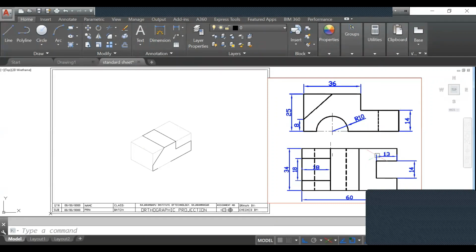So here, if you observe, for this hole, there is one hidden line. Means there is a C channel. The C part is there in the top view at a surface of 14 mm from the bottom, not at the top surface. It is on the 14 mm height only, not on 25 mm height. So I have to start from 14 because this one is 14. So I have to start with this point. Okay. So I will just draw this part from this point, not from this top. I have to draw it from the 14 mm.